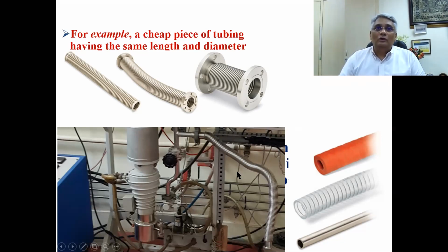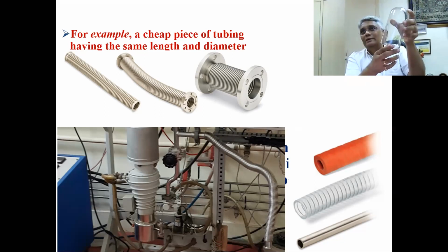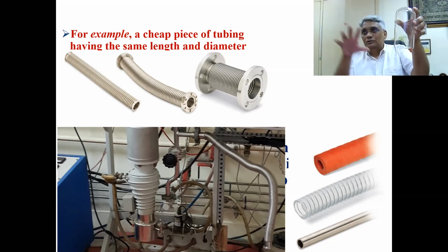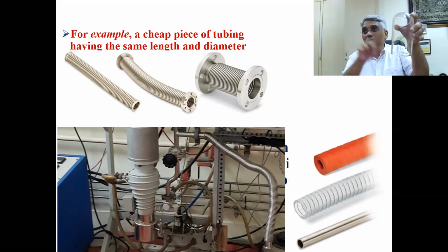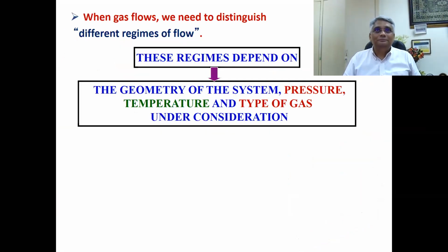The conductance that I talked about, I'll go into more detail on. There are many conductances in a given system, not just one. If the pump is connected directly here, there's only one conductance. But if I have a pipe connecting the chamber to the pump, and there's also a primary pump and a secondary pump, which may be connected in series or parallel, you're increasing the number of conductances. And then there is what is called an effective system conductance.